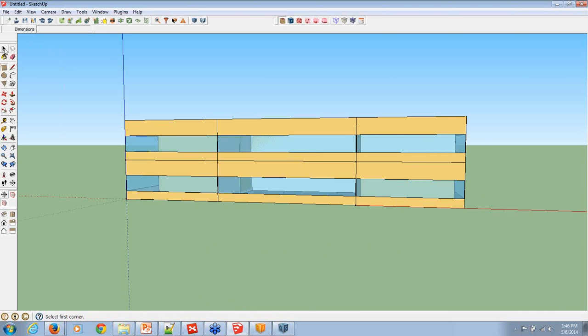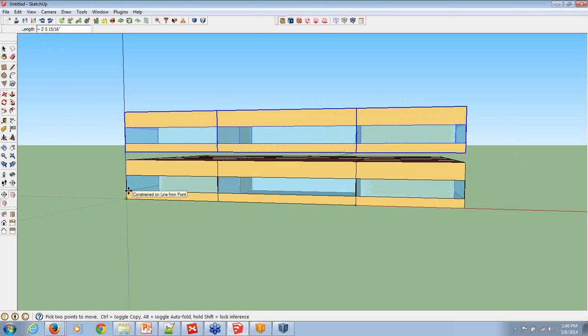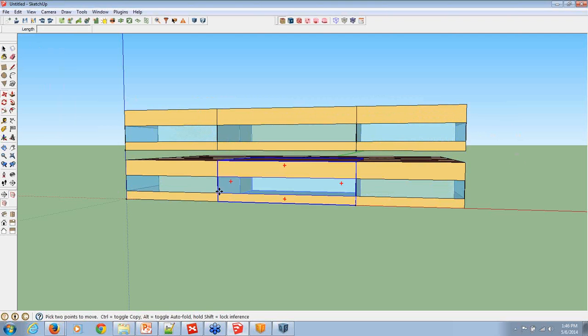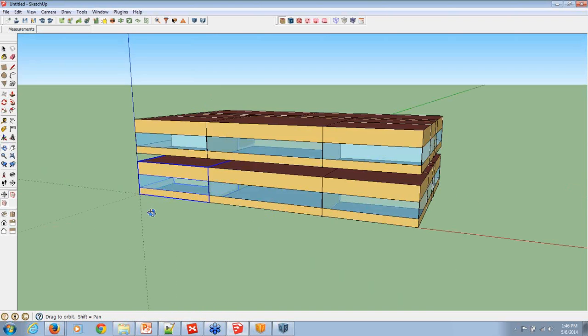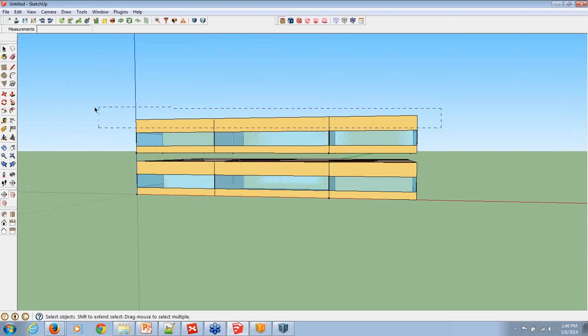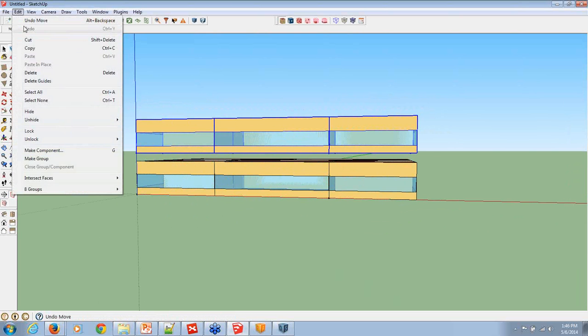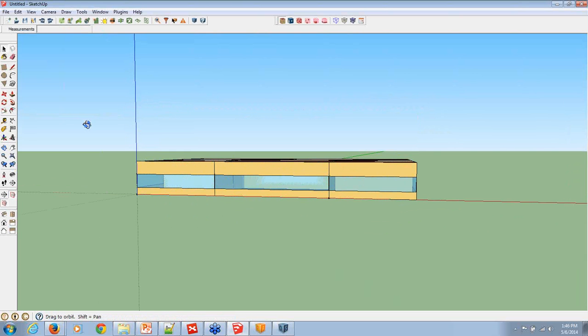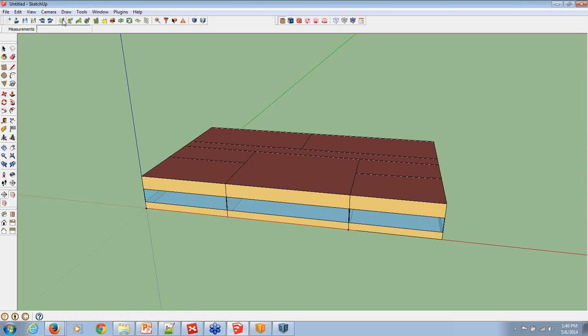I'm going to select, for example, those spaces. I'm going to move them 3 feet in the Z direction. So they're sort of suspended in the air right now. And furthermore, I'm going to hide them so I can work a little bit easier on that plane. So I'm simply going to hide them. Now I'm going to create a new OpenStudio space here at the corner.